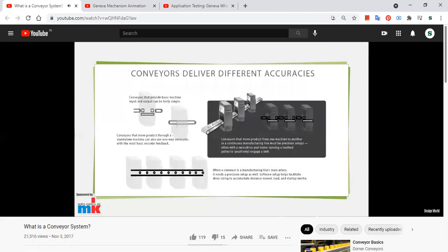How does surrounding equipment interact with the product riding on the conveyor? Conveyor Class 1 includes material handling uses in which the conveyor serves as an artery to transport bulk or discrete product in a steady stream with little interaction along the way. Class 2 includes conveyors that act as bridges to take product from one location or machine to another. Class 3 includes conveyors that take materials into or out of machines or stations. Class 4 includes conveyors that run right through machinery without break.